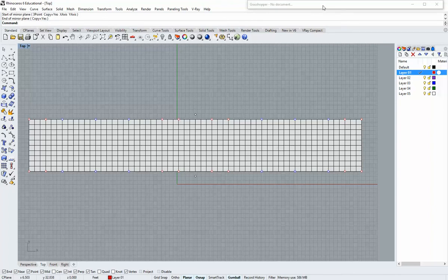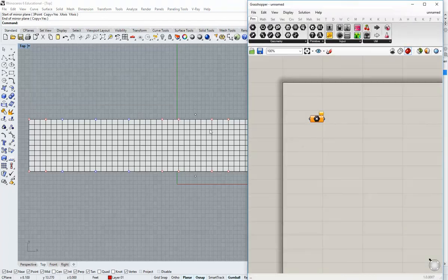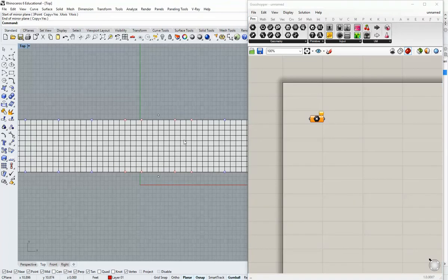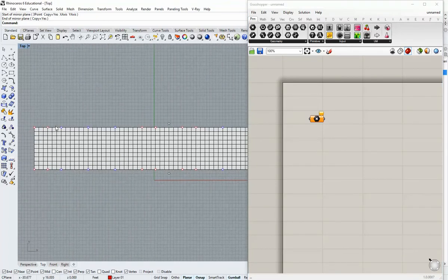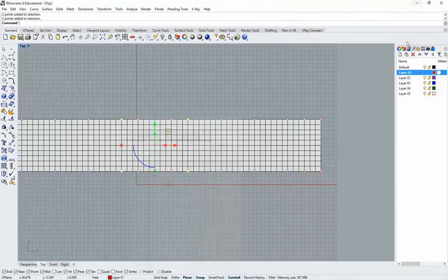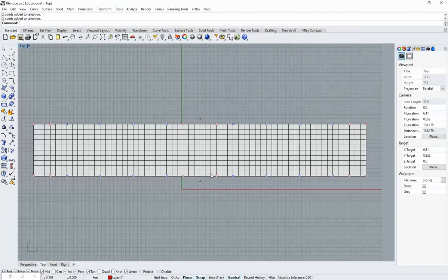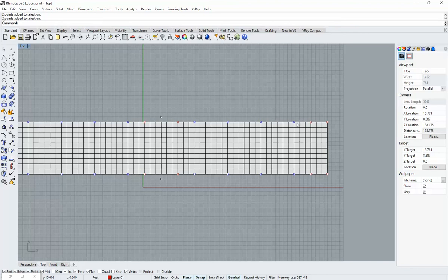Okay, and I'm going to head into Grasshopper here, and I'm going to start drawing these points in. So first I'm going to select those, actually, 1, 2, 3. To make this a little bit easier, I'm going to take the outermost red ones and make them blue. Now that I think about it, it's probably a little cleaner that way, because those are going to go up. I'm trying to distinguish between what points go up and what points go down. In this case, these 4 stay down, these 4 stay down, and this set of 8 stays up, and that goes up as well.